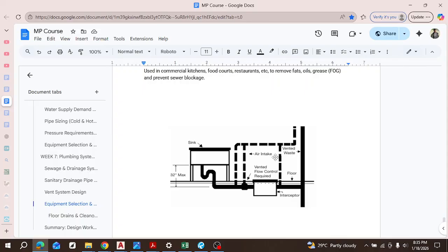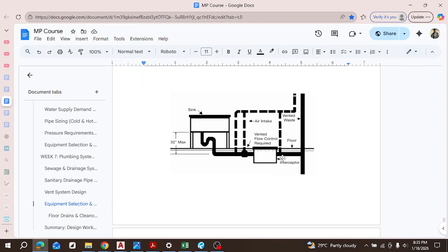Any place that is likely to have a gas buildup, you put your vents. So this is what a circuit vent looks like, because it forms a circuit around it, and you see it is still vented up. So there has to be a place for escape, right? You notice even the pipe that is being released is also being vented, although it's not like a standard vent, but it is vented too, right?